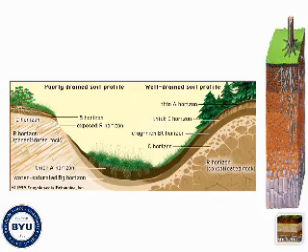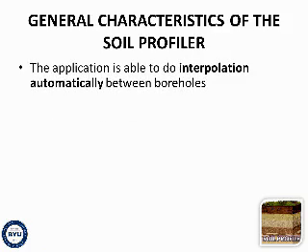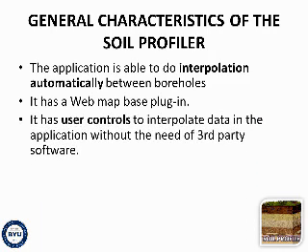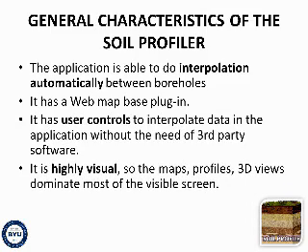The general characteristics of the Soil Profiler are: the application is able to do interpolation automatically between boreholes. It has a web map-based plugin. It has user controls to interpolate data in the application without the need of third-party software. It is highly visual, so the maps, profiles, and 3D views dominate most of the visible screen, and it is very user-friendly.